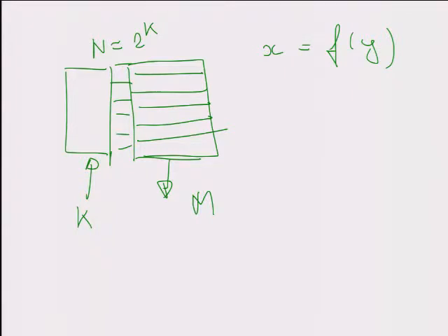So that's the way 99.99 percent of memories work. But now here's another interesting thing you can assume. Suppose I have a memory, but instead of applying an address, I apply the data. I apply a data word, any data word, and the output is going to be the address of where that data might be stored in your memory. It's the opposite. You apply the data and say, if that data is stored somewhere in the memory, tell me where it is.